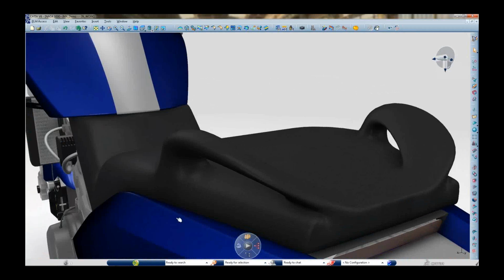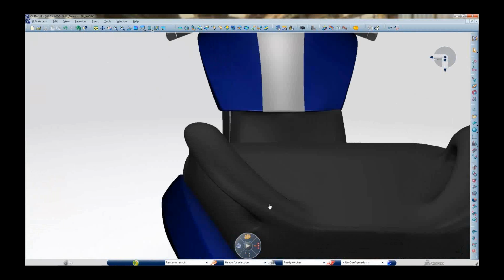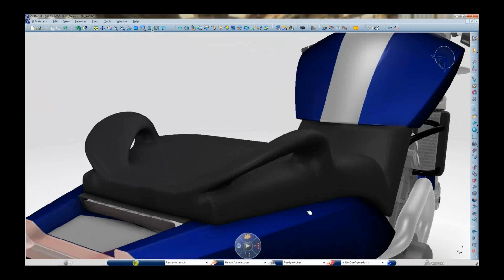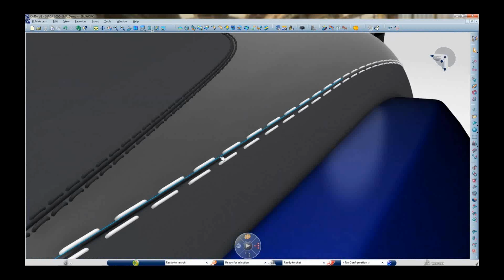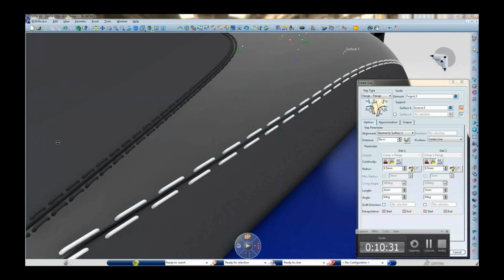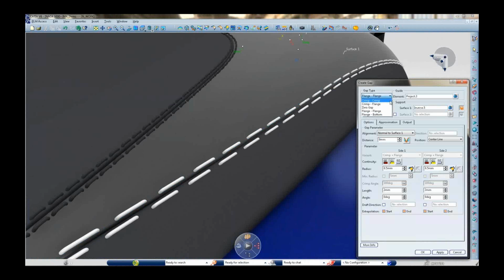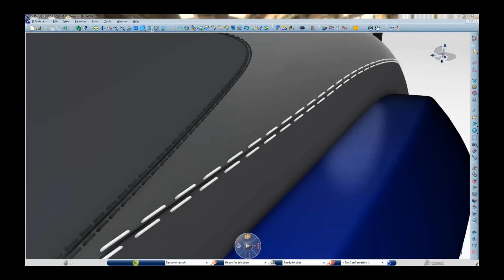So it's based on a mathematics called the subdivision surfaces, which is very similar to virtual clay modeling. So here we end up to a more precise and final project. And the beauty of this mathematics being integrated within CATIA is that at any time you can use any other tools of CATIA. For example, here we are using a gap feature coming from the CATIA Icem tool that will also work automatically on these subdivision surfaces. And then you can relaunch this command at any time to change the gap on this subdivision surface.